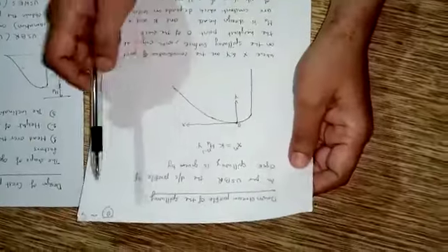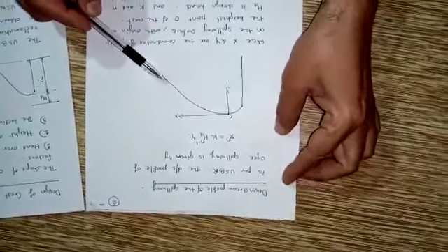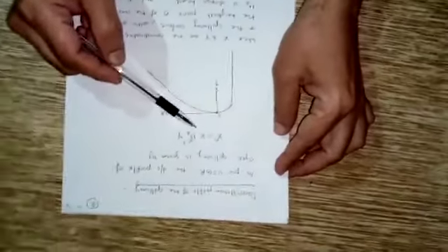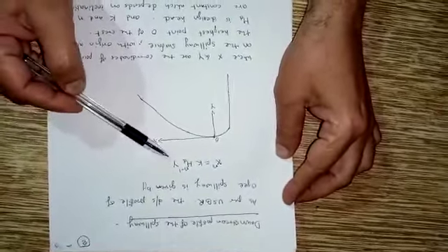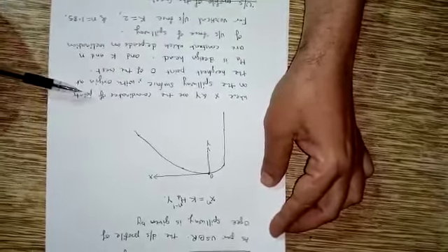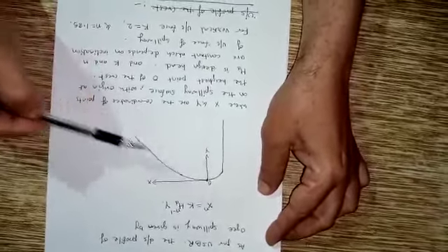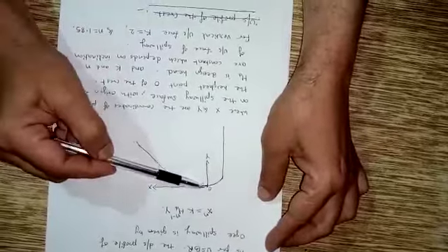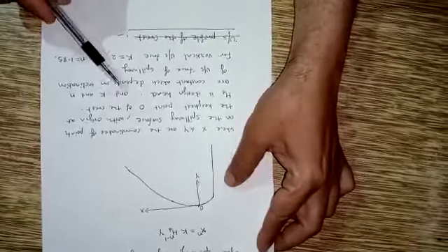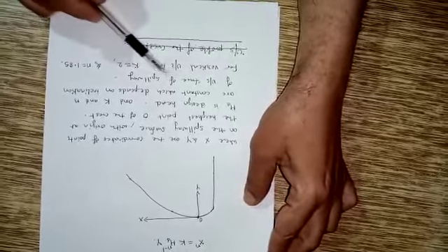According to USBR, the downstream profile of the spillway is given by the equation x^n = K HD^(n-1) y, where x and y are the coordinates of the point on the spillway surface with origin at the highest point O of the crest, HD is the design head, and K and n are constants which depend on the inclination of the upstream face of the spillway.